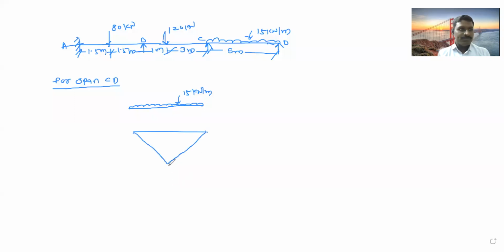So if you see, this is the basic mechanism for the beam. Then the UDL is there. What we generally do when a UDL is there is convert it into a point load. While converting into a point load, this point load acts at a distance from the continuous support, at 0.586 L from the internal or continuous support.